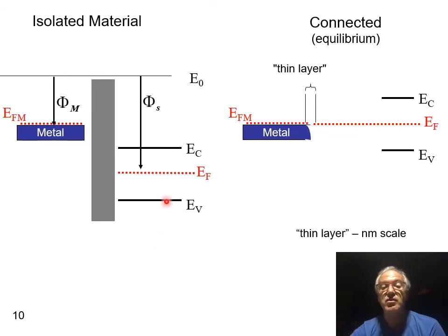And basically what happens usually is really a lot of charge accumulates at the interface, and because the density is so high, it creates band bending, which is very steep. And basically we arrive at a very thin layer where the bands are really bent very sharply across.